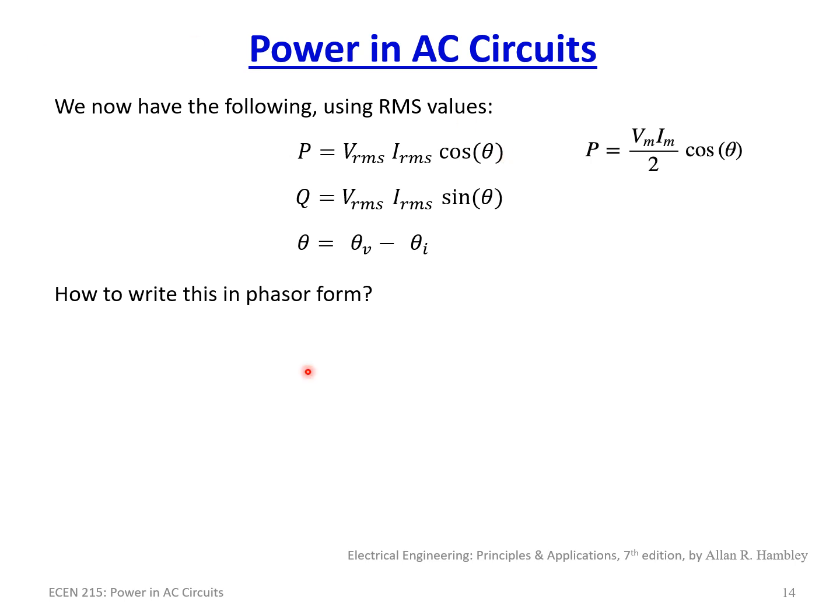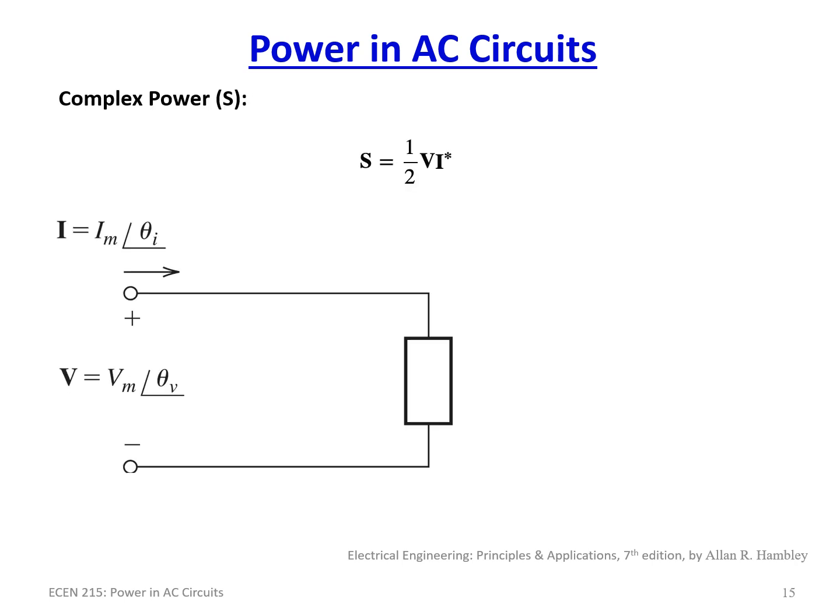So let's take a look at how we can do this, and this is known as complex power. We want to work with voltage and current as phasors in their complex form straight out. As it works out, the equation for complex power has the value S, just so we can separate it from everything we've talked about so far, and it's equal to 1/2 V times I asterisk.